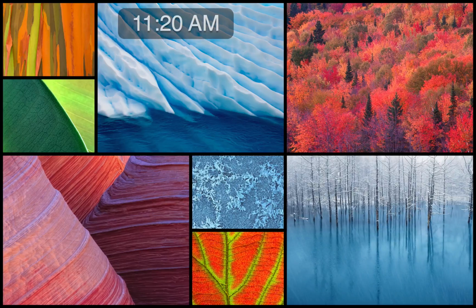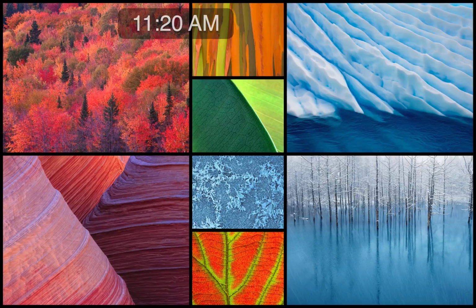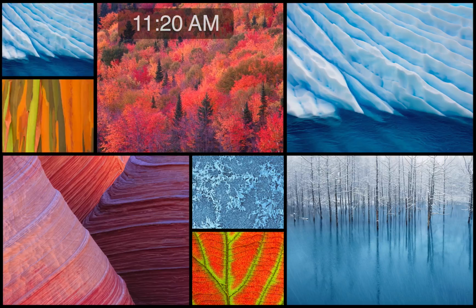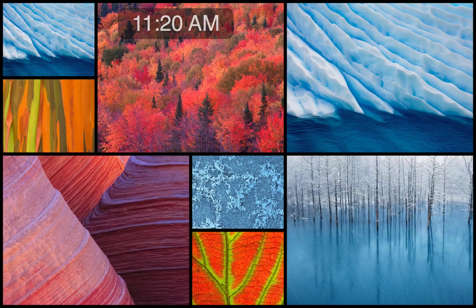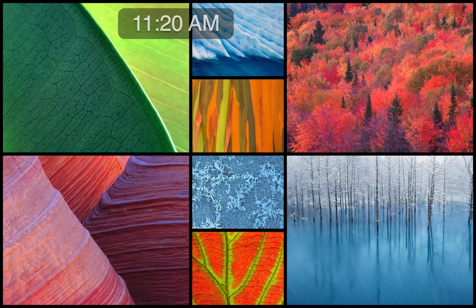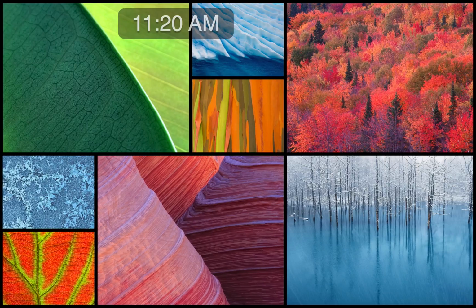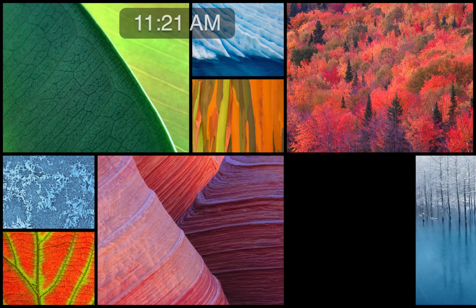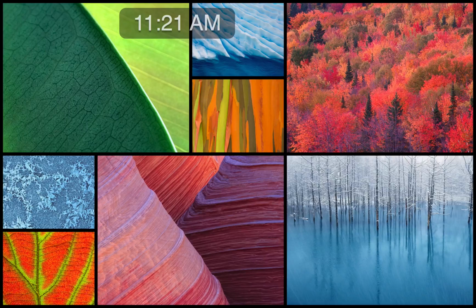So I am going to copy this 3.5 inches over, okay, to get the other side of the wall. Then I'm going to copy. What am I going to do with this, guys? Hooray! Yeah. Then we're going to erase 6 of these guys, and we're going to go first to second, and we're going to do 2 feet. Then we're going to select them all, and then what are we gonna do now? Copy it 1.5 inch. Yeah, and it goes to the left. So we're gonna copy this 1.5 inches.